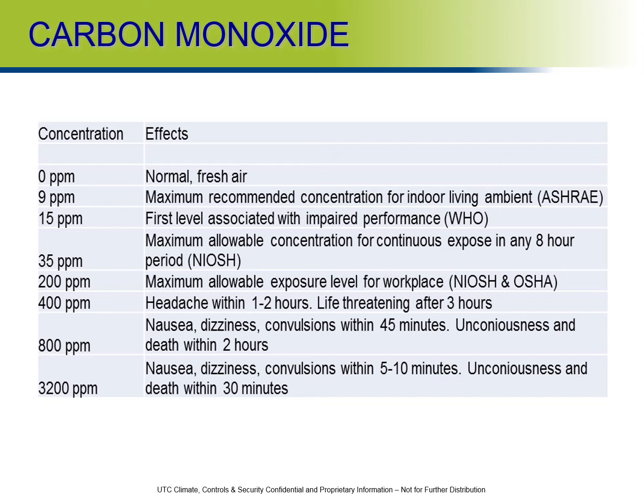At 400 parts per million, you could start to experience a headache within 1 to 2 hours, and it becomes life-threatening after about 3 hours of exposure. At 800 parts per million, you can start to experience nausea, dizziness, and convulsions within 45 minutes, and unconsciousness and death within a 2-hour period of exposure. At 3,200 parts per million, you could experience those same symptoms, however now within a 5 to 10 minute period, and unconsciousness and death within a period of 30 minutes of exposure.